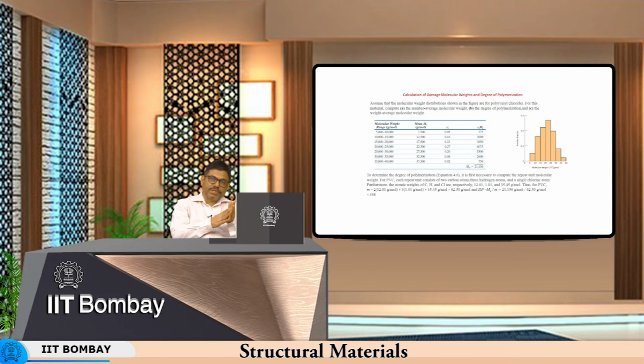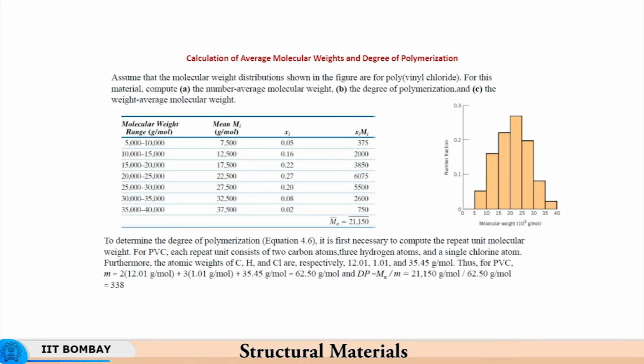The number of repetitions will be less. So the macromolecule will become smaller and smaller, and its melting point will become lower and lower. So if you want to adjust the melting point of a given polymer, then it is important to have a balanced mix between relatively high weight molecules and relatively low weight molecules.